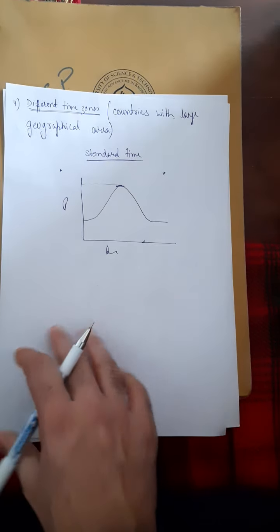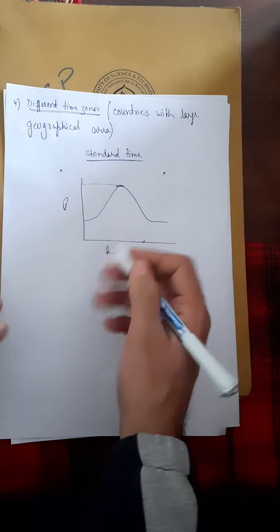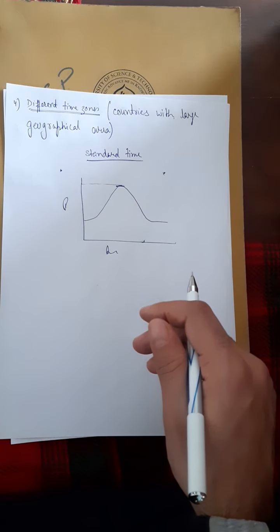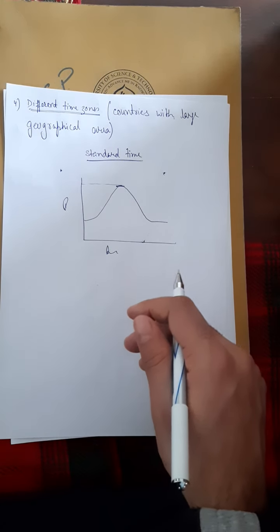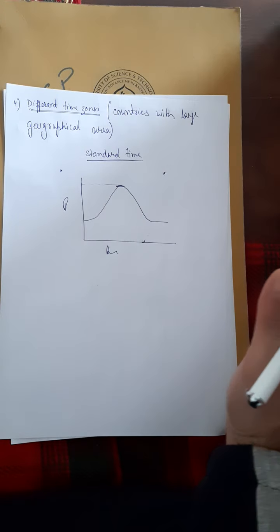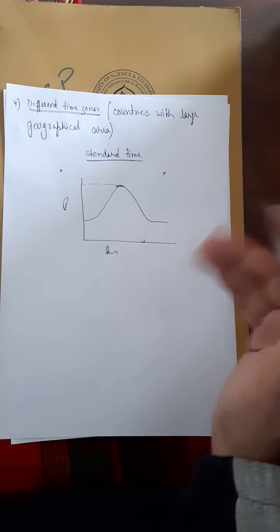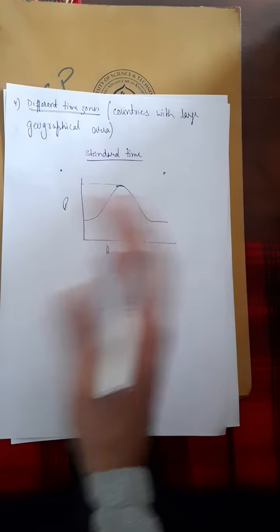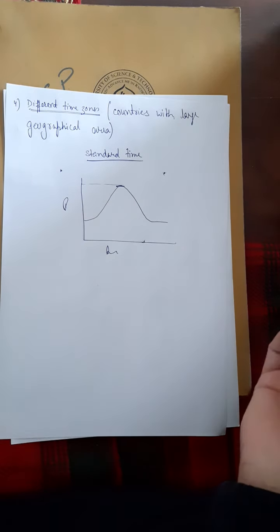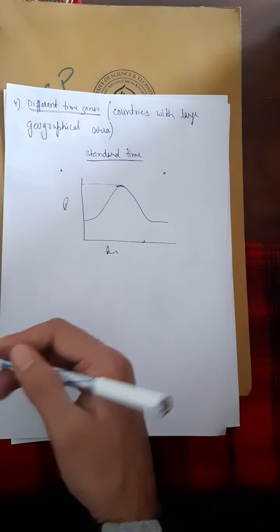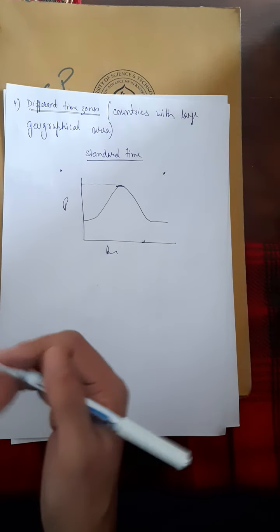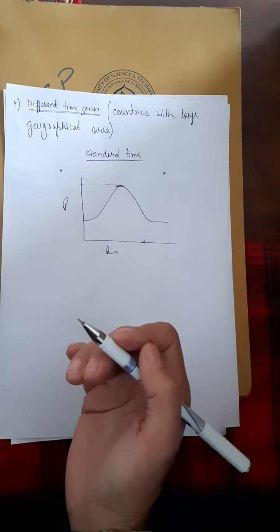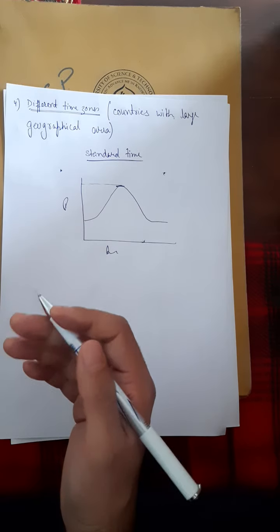Okay, so what I can do, as can be seen, is divide the country into 2 time zones. The left half of the country has one standard time, and the right half of the country has another standard time. Obviously, in both regions the day will start at different times, and their peak loads will occur at different times.